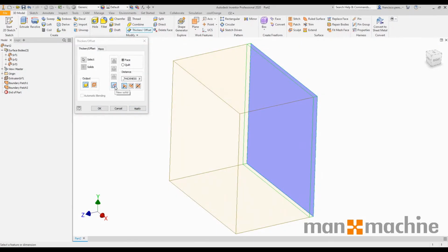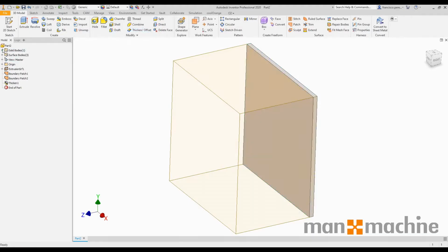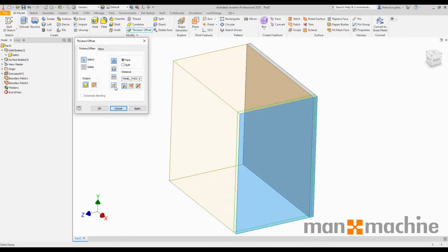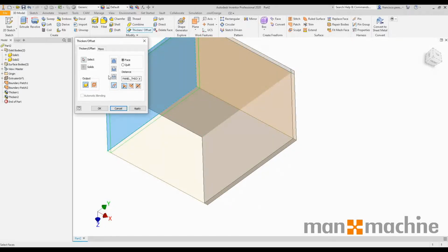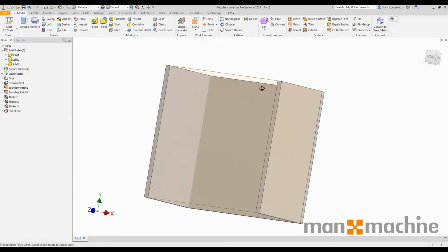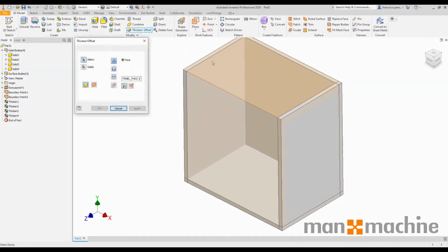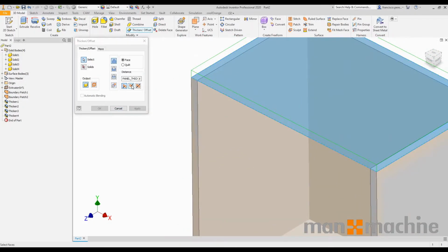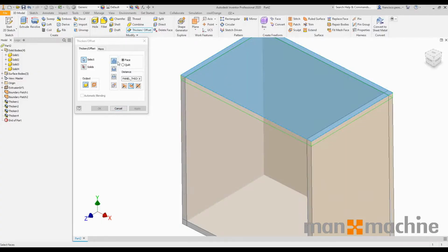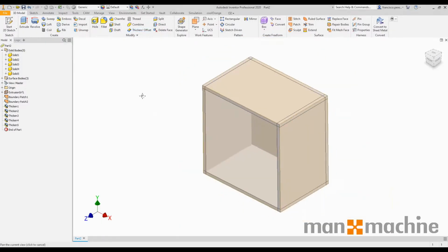And by default, for the first one, it'll create a new solid body, in which case, if we go to the solid body list, we can see the solid body there. We're going to do that for each of the panels, but we're going to notice something wrong about this. In each panel, we're going to click New Solid so that it creates a separate new solid body. So panel, make sure they're all going in the right direction. Panel, thicken, there we go, looking good. Thicken up the top. Aha, you don't get away from me that easy, panel. We make sure it's going in the right direction. Make sure it's a new solid body. Wonderful. So far, so good.